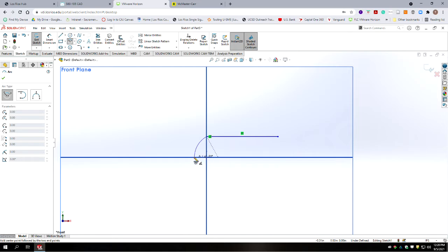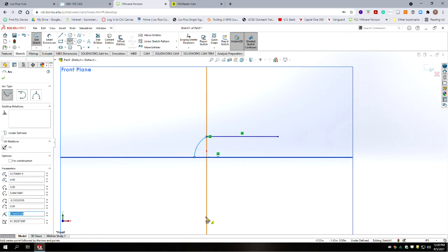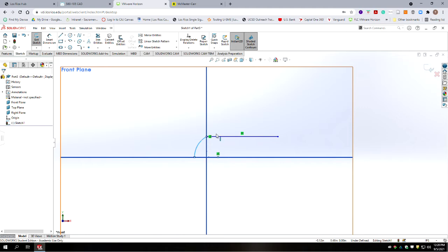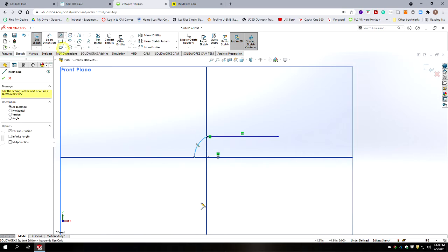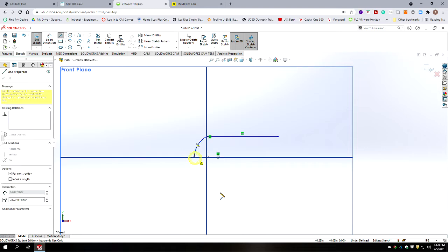We're going to snap to the center line. We do not want the tangent relationship here because they are not tangent in the drawing. Okay. Alright, so if we go back to our drawing, actually I'm sorry, let's go ahead and do our revolve center line, and that's going to have another purpose, which you'll see here, than it did in the prior ones.